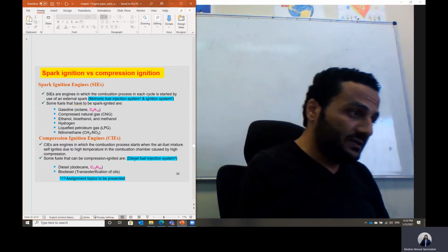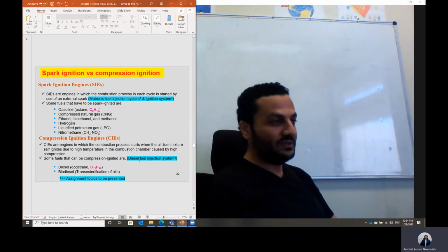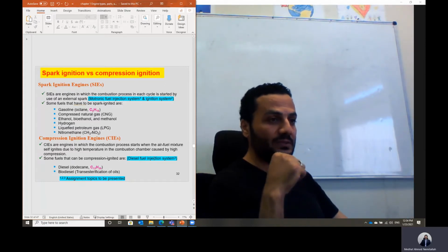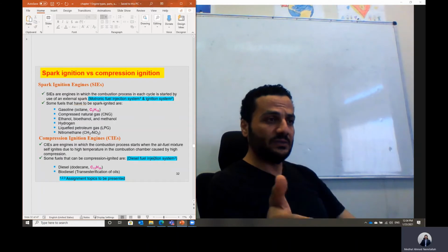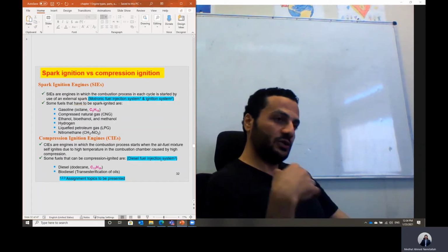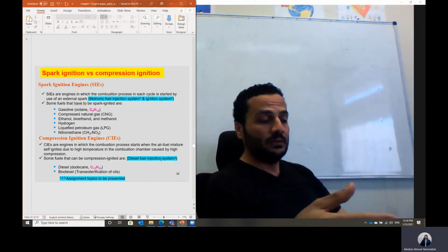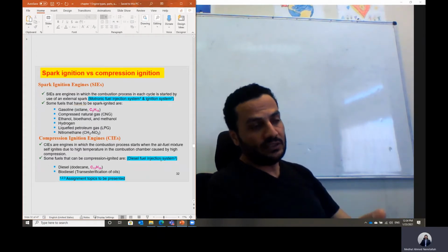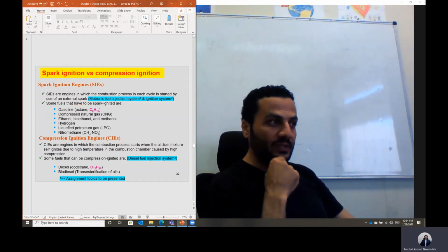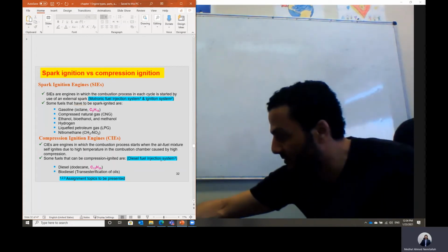Okay, and that's why we said that we cannot cover all of the topics. Those are big systems. We have different fuel injection systems for diesel. We have the inline pump system, we have the common rail system, and then we have the distributor pump injection system for the diesel engine. We want to see those systems, and you can give us an idea about how the fuel is injected and metered to the engine depending on the engine load and the engine speed. Okay, here I can give you an idea about the throttle valve in case of gasoline engine.